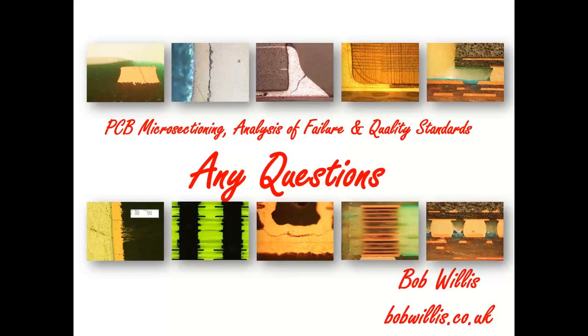potting operation. I sometimes put epoxy onto the surface of the board, let it capillary underneath the sample, and let it cure. So I'm sticking the component to the board and I'm trapping everything. I'm making sure that nothing's going to move. And then what I would do is prepare the sample, cut the sample close to where I want to examine, and then pot it again.